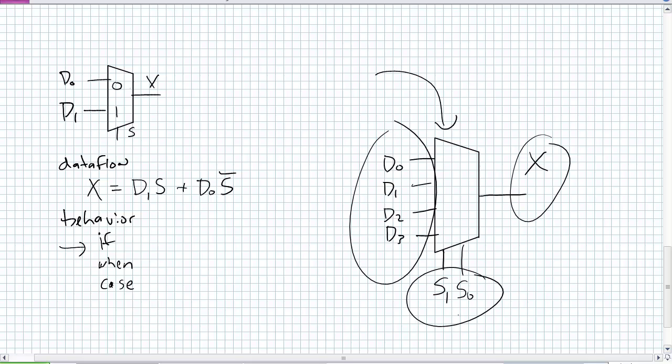What we're going to try to do for this take-home exercise is use any one of the behavioral definitions, what I'm about to show you here, as a core for your 2-to-1 multiplexer, and then use it in a structural approach. So I'm combining behavioral and structural as opposed to data flow and structural. With behavioral, if you remember, we did that truth table in Unit 5, entering a truth table in VHDL using that select assignment. So we could do that too.